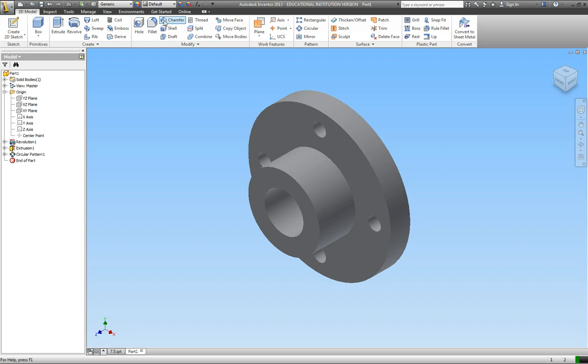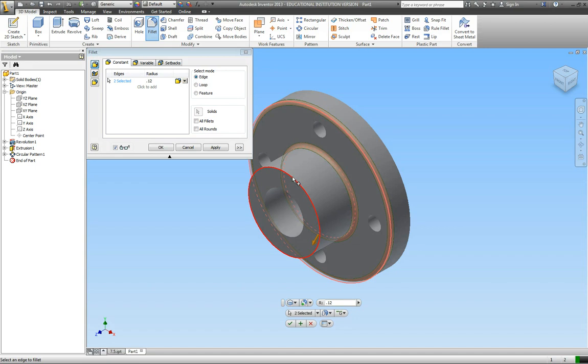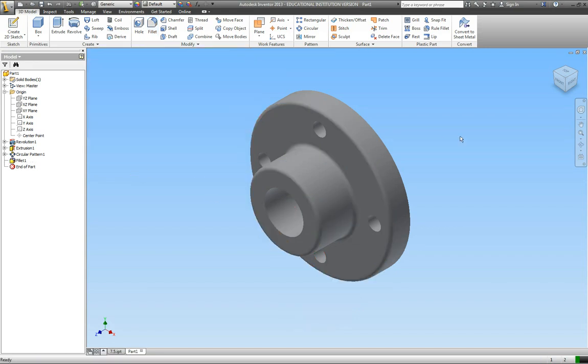of the definition. So let's use the 3D fillet in Inventor. It's on the Modify panel. The radius should be 0.12, so I'll just click here and type 0.12. And the select mode edge is fine. Okay, so I'll just go around and click on the appropriate edges, and when I select the appropriate edges, just select OK, and you can see that the 3D fillets were created for me as shown in the text. Okay, so pretty easy part of construction.